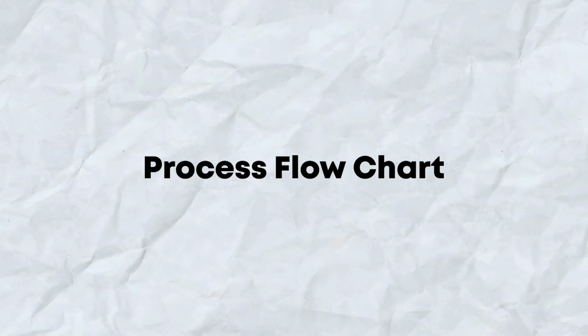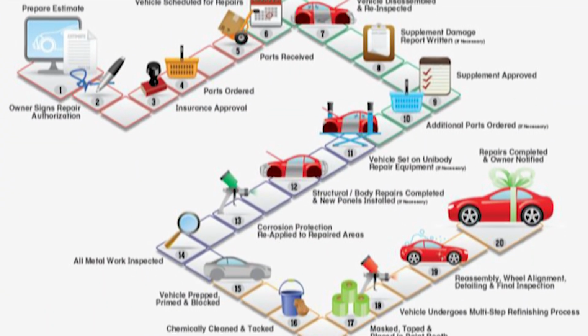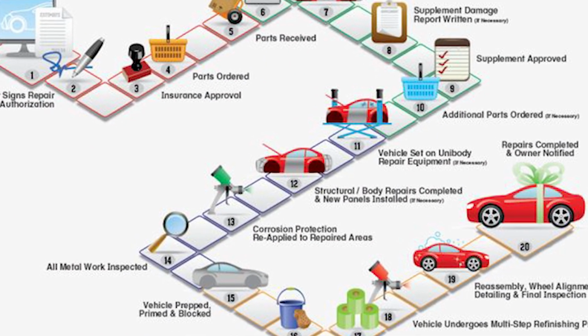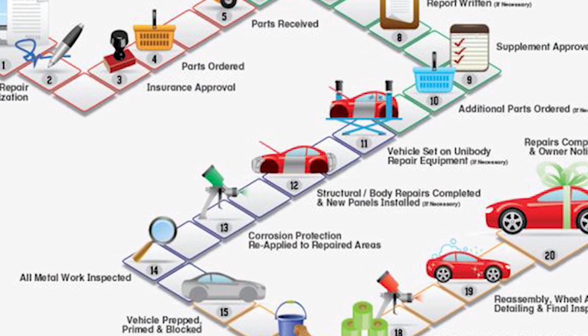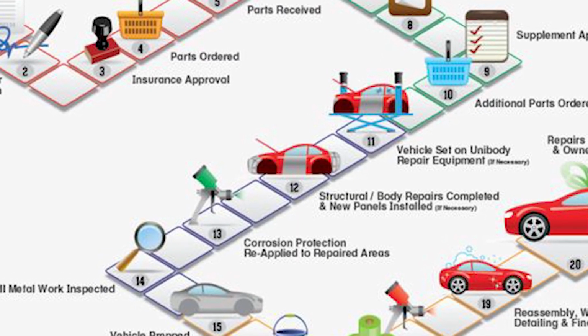The 3rd output is talking with respect to the process flow chart. Now, if you look into appendix A6, which is there in the APQP 3rd edition, you will find a detailed list of so many points which are to be considered with respect to the process flow chart. Now, when we talk about the process flow chart, what is it talking about? It is talking about the manufacturing process, when you are making this car, there are so many processes starting from incoming inspection till dispatch, how the flow of the material will be there. And then when the material is flowing, what are the different stations, what are the different steps which are there when we are producing a particular car.